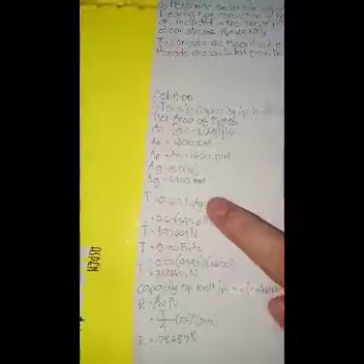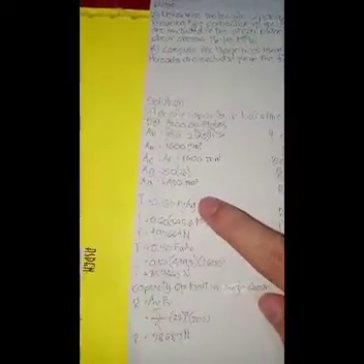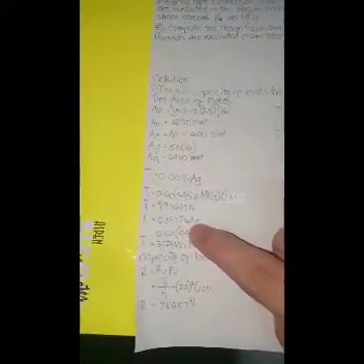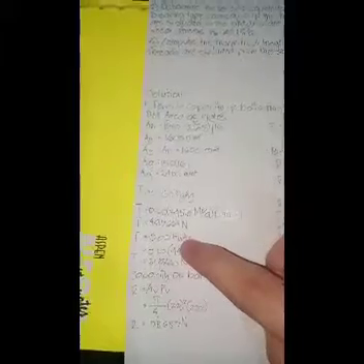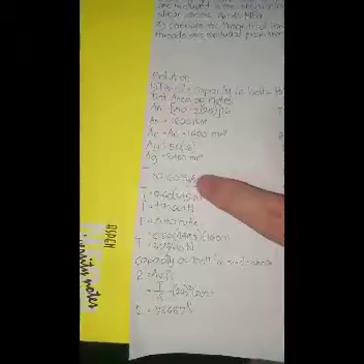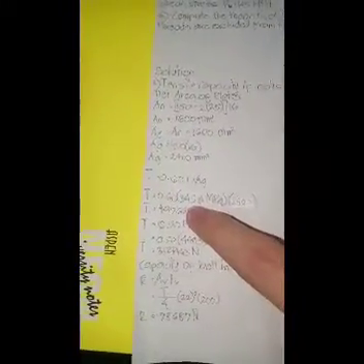Then, T is equal to 0.60 F sub y A sub g or 0.50 F sub u A sub e, which comes from the NSCP specification, so it is a constant. Substituting into 0.60 times F sub y times A sub g, the answer is 497,664 Newton.